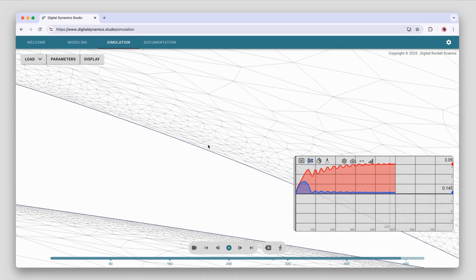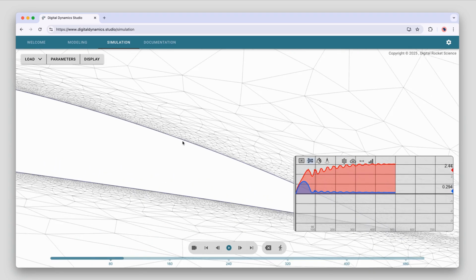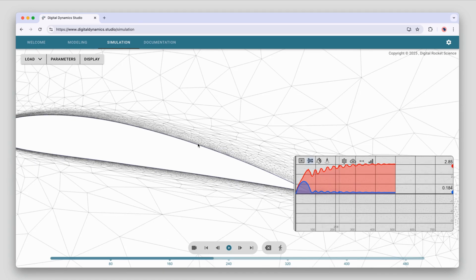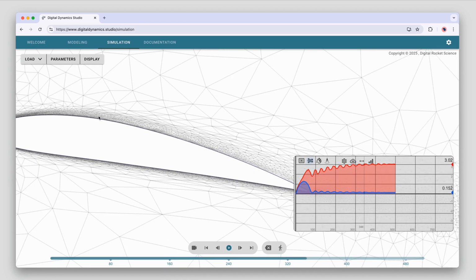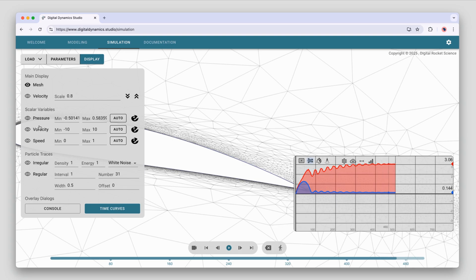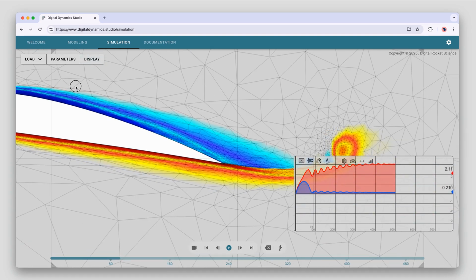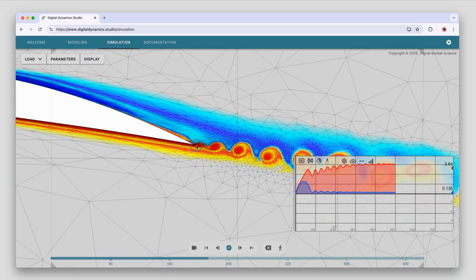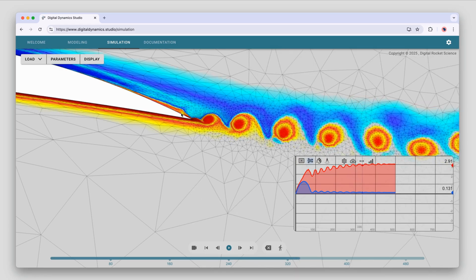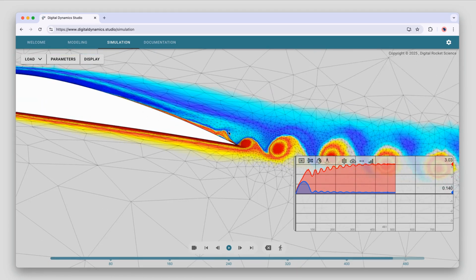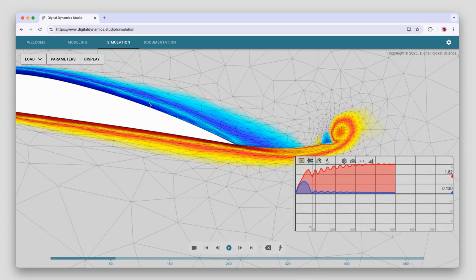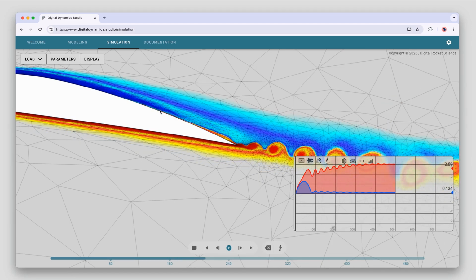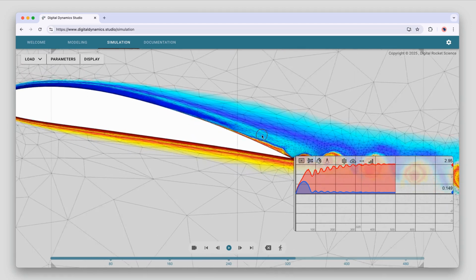The size of the mesh will have to be much smaller than this in these kinds of simulations. So the mesh is a little bit thicker than it should be around the airfoil, and because of that, we are probably getting more separation here than we normally would. The separation is probably not realistic. It's just the fact that the mesh that we have can't get small enough to capture the boundary layer in these regions. But it's pretty close.